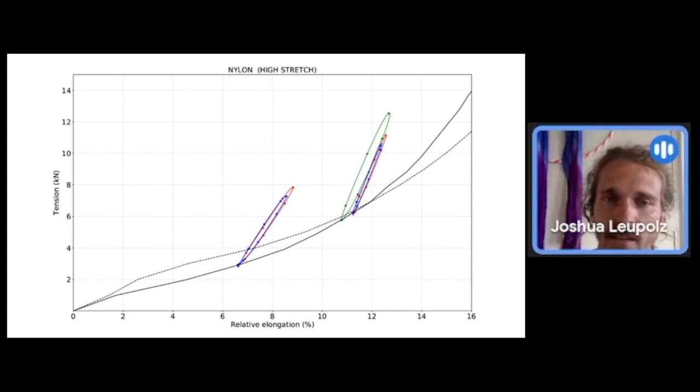The base takeaway is the same: you drop a webbing and you get quite high forces. And there you see clearly a difference between the black line, when you stretch out the webbing slowly to 7 kilonewton, you expect to have like 13% stretch.